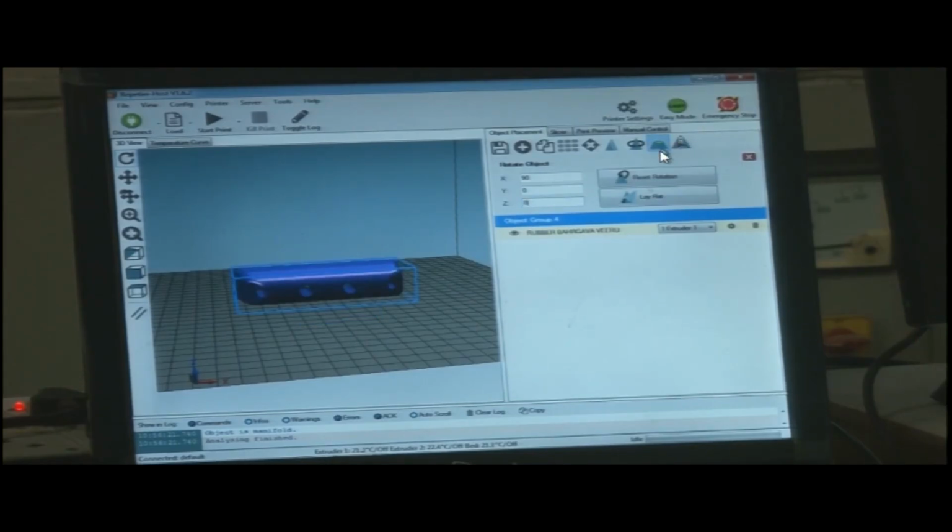So next is view cross section. This icon is view cross section. Sometimes we need to see what is in the inside portion of the job. For example, we have a CAD model from the customer. The customer has just made this model and brought it for us, so we are not aware of what the profile inside is. Are there any holes, some pockets, some countersink holes?